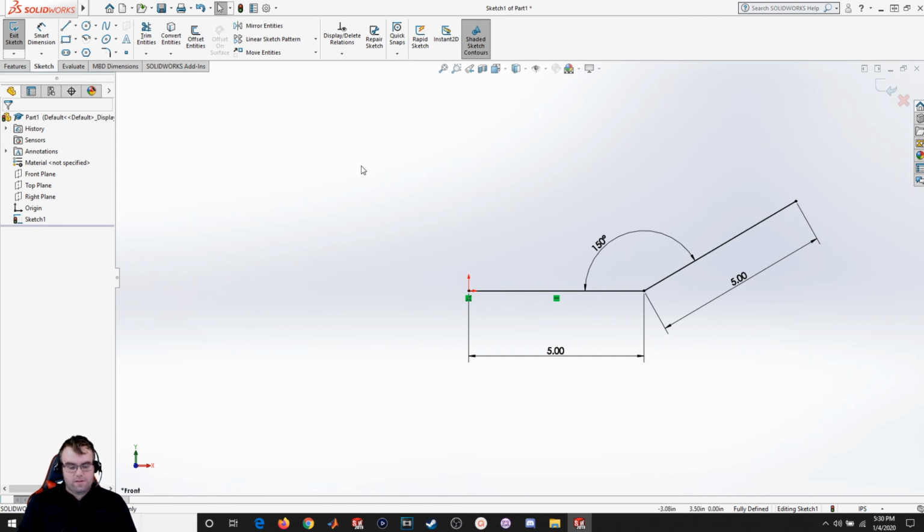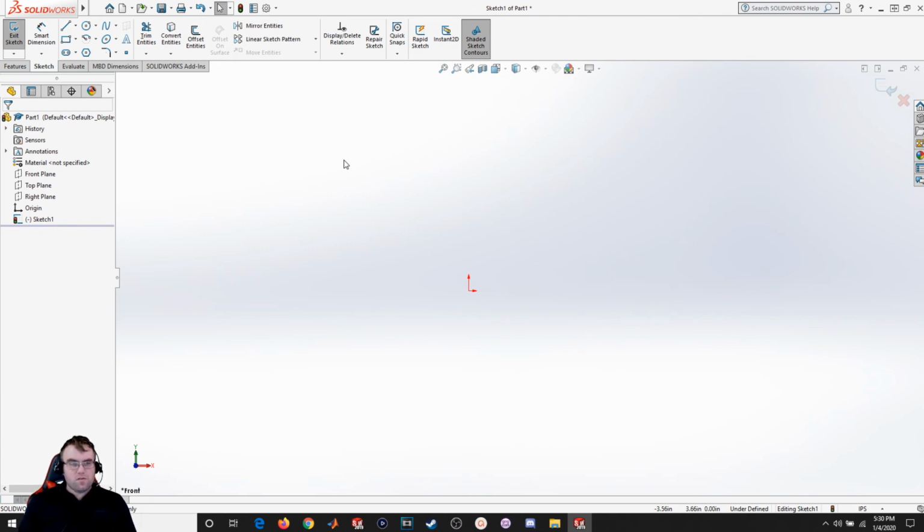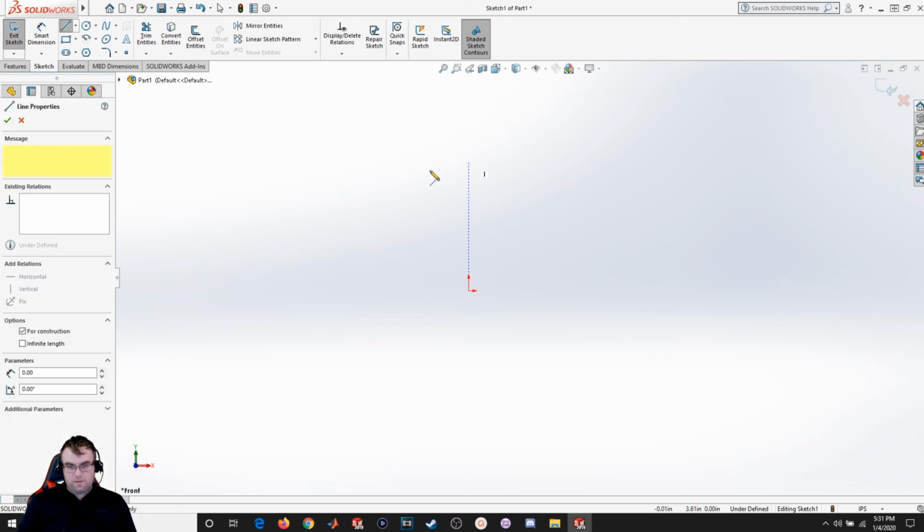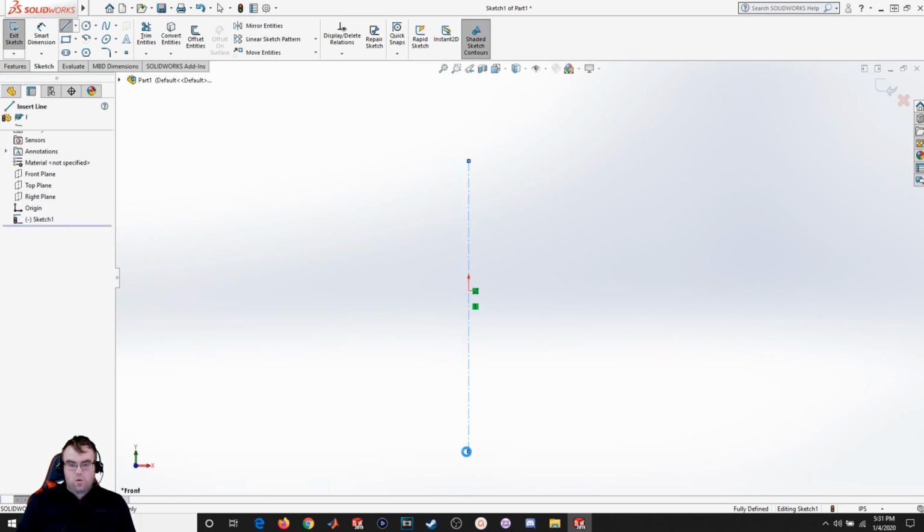Now the last relation I'm going to go over in this video is a very useful and powerful relation. It's called symmetry. So let's go ahead and delete this. Symmetry requires first a line of symmetry. So we're going to create a center line. I'm just going to mouse over the origin. You're going to see that it's guessing that I want it to be vertical with this origin point, which is correct. Left click, and I'm just going to drag a line all the way through. It'll snap to go through the origin. That's what I want. That's going to be my line of symmetry for what I'm about to create.